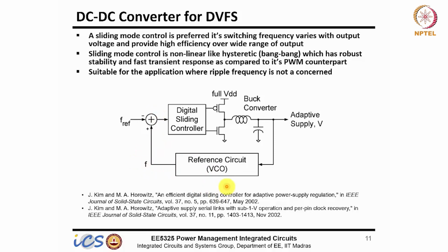The reason we are using a VCO is because your delays are measured in terms of inverters actually. So if this VCO is implemented using a ring oscillator, which is nothing but cascaded inverters, then it will represent your digital circuitry, whatever logic gates and everything. If you can run this at a lower voltage, you can run the other circuitry also at the same voltage. If your process changes, let's say it went to a slower corner, then this frequency will automatically go down and this loop will force this voltage to go high so that it is again locked at 1 gigahertz.